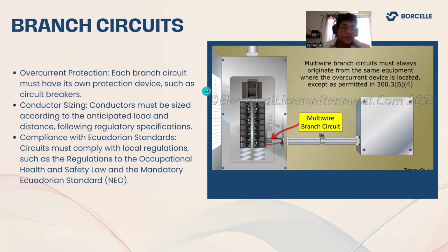Well, we have overcurrent protection. Each branch circuit must have a protection device such as circuit breakers. Conductors must be sized according to the anticipated load and distance, following regulations and specifications according to the NEC and complying with Ecuadorian standards. Circuits must comply with local regulations, such as the occupational health and safety law and mandatory Ecuadorian standards.